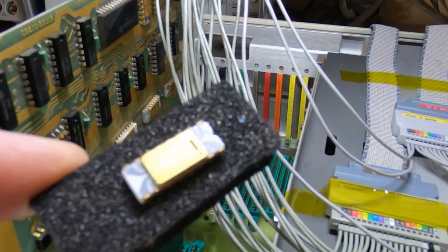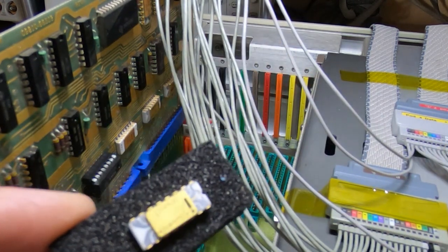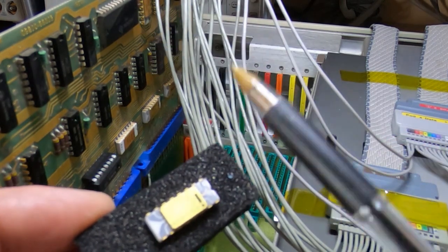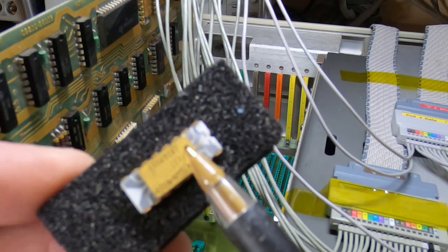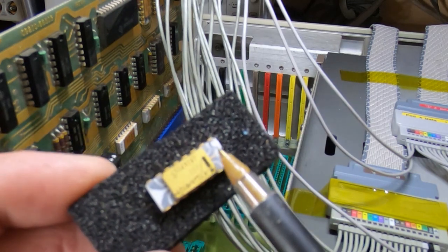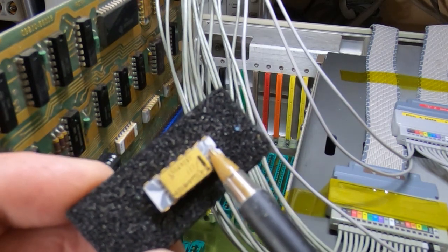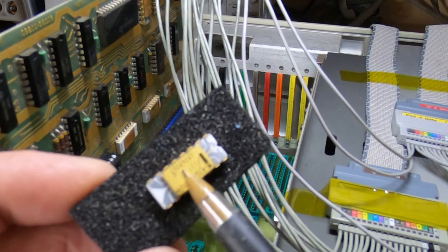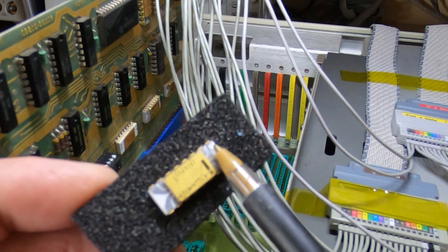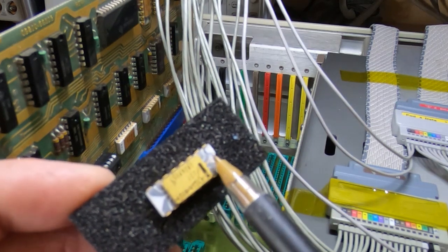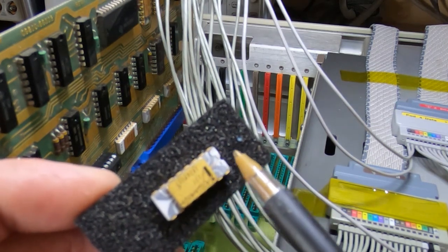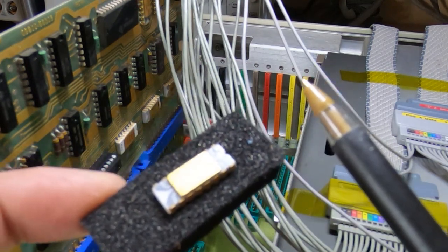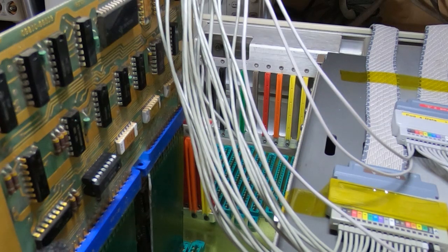I think this is partially failing, and the loading on the programmer is not the same as on the actual card. I'm looking at it very closely. I don't know if this will come out on camera, but pin 1, or connection to pin 1, you can see these grey traces. These are conductive traces. Seems to be damaged where it's going to pin 1, so I think it's just only a partial connection there. But either way, it works in the programmer but not in the card.